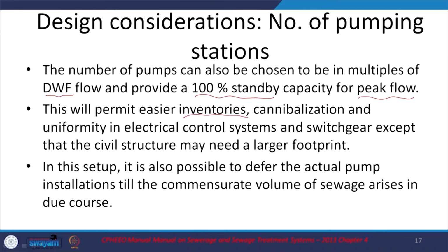And with this setup, it is possible that we do not need to put in the pump installation until the volume increases, as I am designing my sewage treatment plant for a 30-year period. But right now the population is less, which does not mean I should not start the sewage treatment, right. So, in this setup, as you see, you can keep increasing the capacity as and when the flow increases or is estimated to increase, rather than having all the capital spent right away and thus incurring costs. So, that is one aspect to keep in mind.